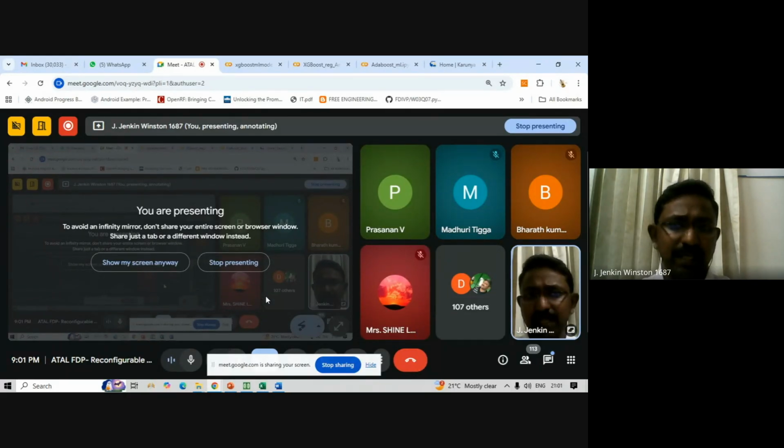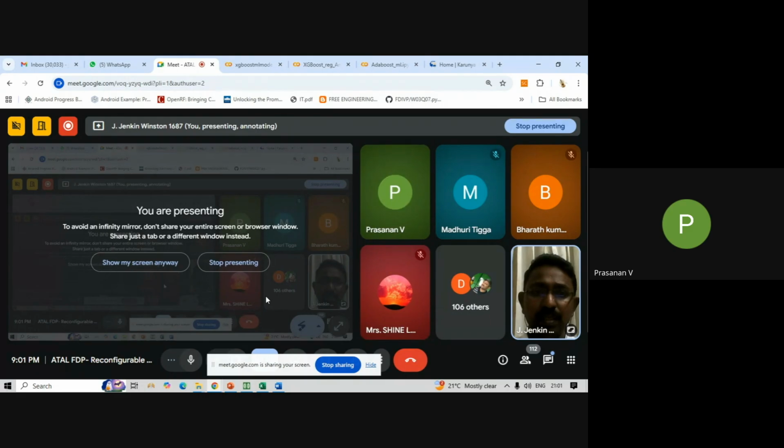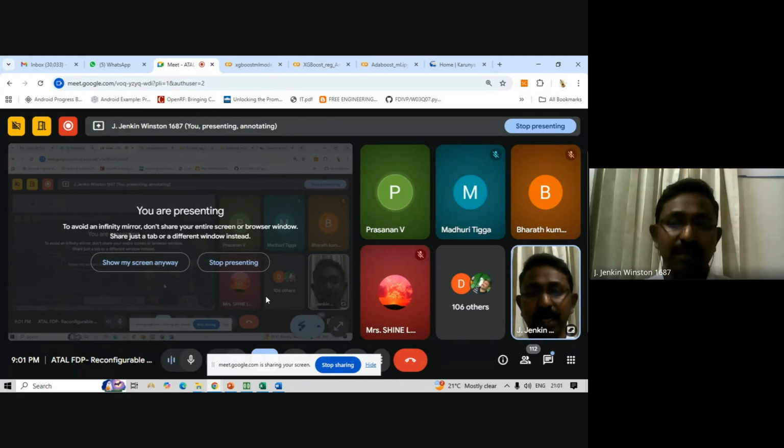Okay, and I have given only one target value here. That is, I have optimized my design only with respect to gain. Maybe in reconfigurable antennas, you would also need to improve the gain of the antenna apart from the return loss. Am I right, sir? Yes, sir. You can try to have another target column.